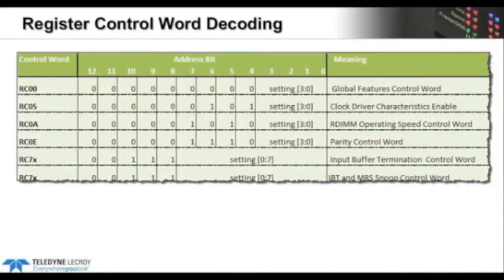All right, so there are 27 register control words, really more than I can list. This table just gives you a few examples. I'm actually only showing the register address bits. So these bits here are the part that contains the payload, right? The rest of the address just identifies which command. So of the 27 commands, about half use a 4-bit payload, and the other half use an 8-bit word size. These settings are what gets written into the register.